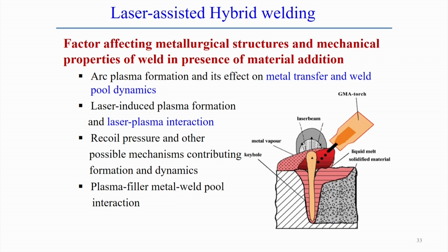The interaction actually helps the absorption of energy during the welding process. Third point is the recoil pressure and other possible phenomena in the formation of the weld pool dynamics, basically the influence of any kind of shielding gas, which creates more complexity in this process.